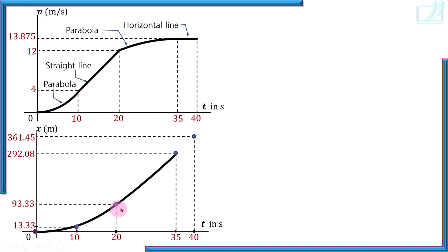You should not get sharp corners here. A sharp corner means a sudden change in slope of the curve, and a sudden change in slope means a sudden change in velocity. Is there anywhere a sudden change in velocity, that is, a vertical line in the VT diagram? No. So there must not be sharp corners here.